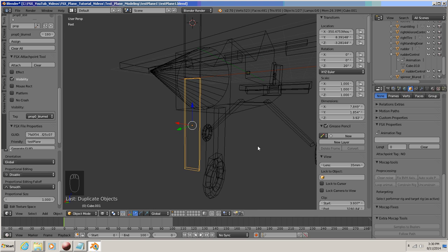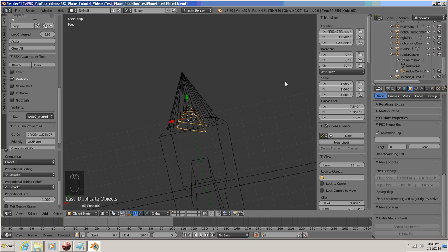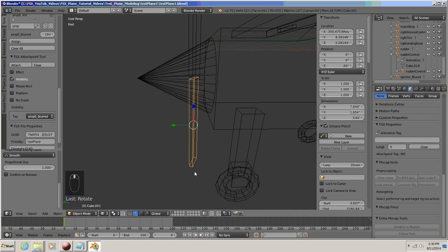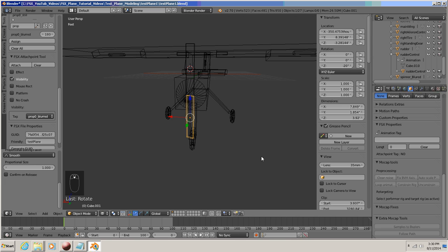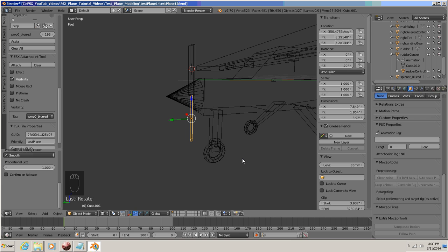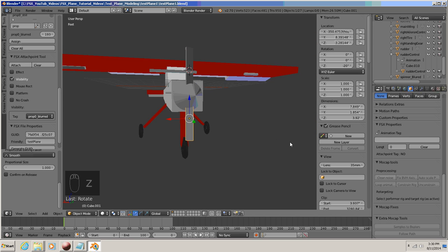And we can go back into perspective mode, and you see both our props are going the same direction. That won't work. So let's go underneath of it so you can see it a little better. We're going to hit Rotate on the Z-axis -40 degrees and enter. Now we put the pitch more like what it should be. Now let's go out of wireframe back into solid mode. So hit Z so you can see what it's going to look like.